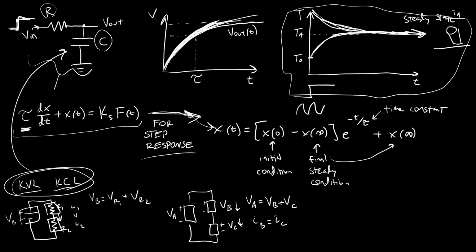There's a time constant to them, because even in a circuit without a physical capacitor that you've put in a breadboard, there is something called stray capacitance, so basically just extra capacitance in a circuit between parallel wires or parallel rows in a breadboard or something. So the real world, just like how the real world has friction, even though you model things without friction in lots of physics problems, real circuits are going to have capacitance and things aren't going to change instantaneously. So a little reminder of why you care about this before we dive more into the analysis on a clean slide.